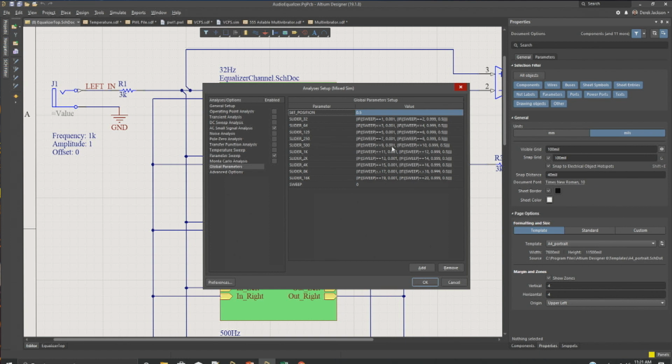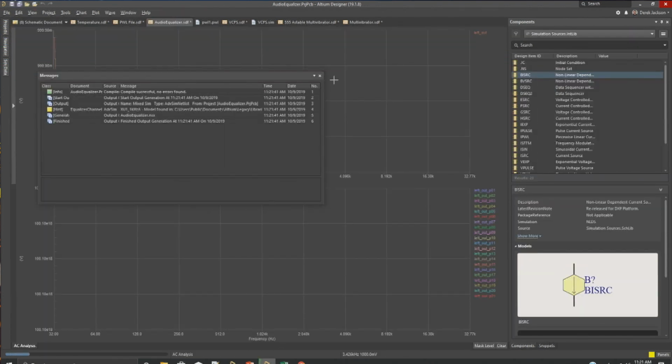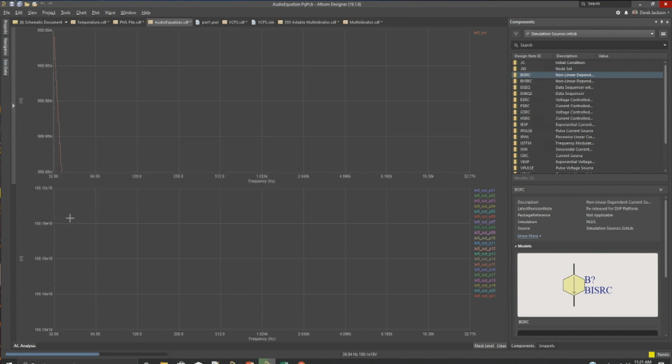So you can see here what it's checking: it checks the sweep value, whether it's 0, or 2, 4, 6, and it goes through and varies all the values to cycle through the steps of the audio equalizer, and then when you run that, it'll show all of the different parameters from the results here. Just right click and fit document.